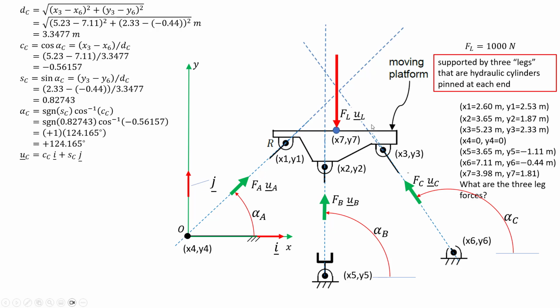Here we will use point 6 as the reference, x6, y6, and we will be looking at what point 3, x3, y3 is doing relative to that. This one's getting out of the first quadrant now, and we're looking at a negative delta x, because x3 minus x6 is going to be a negative value, and I divide by the distance between. So I'm looking at x3, y3 and x6, y6, and the distance between those points.